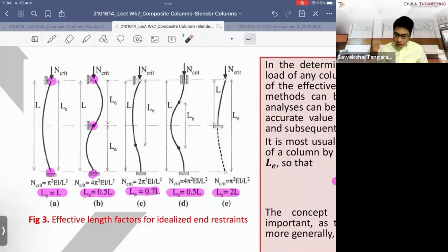When you have the fixed end, this is the worst case. You have the fixed end here and a released end, a free end, at the other side, so the effective length becomes 2 times, and this is one of the worst cases. That's why when we design a cantilever column, which stands straight up with the end at the top free, right?